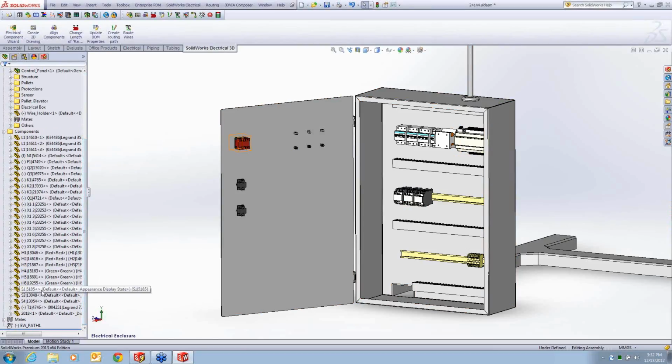Now when it comes to actually routing that information and sending the wires that I defined in the 2D sketch diagram, I can have it do an automatic routing, but I can also have it go along a specified routing path. What I'll show you here is if I select down here, you can see I've got the highlighted in orange. That is a routing path that I've created.